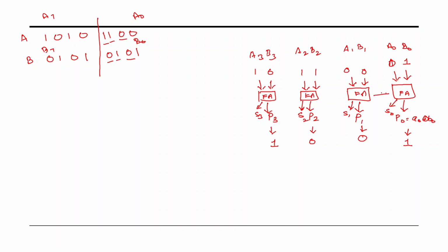Yes, not. Then carry will propagate as usual. The carry will propagate as usual, like a normal ripple carry adder. Seen as a 0. So now, these are propagate terms, right? 1, 0, 0, 1. This all will go to a reduction AND.